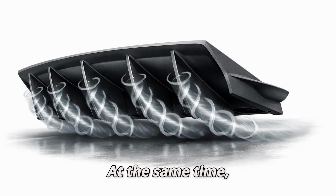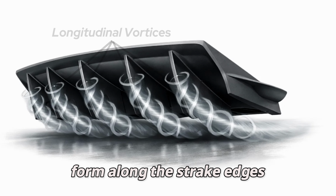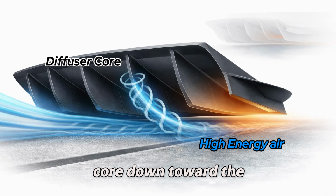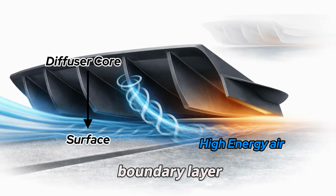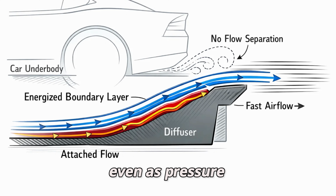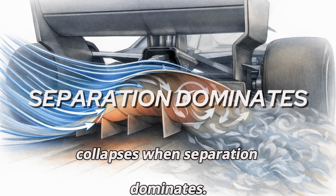At the same time, strong longitudinal vortices form along the strake edges, pulling higher energy air from the diffuser core down toward the surface and feeding momentum back into the boundary layer. This continuous re-energization helps the flow remain attached even as pressure rises aggressively through the diffuser. But even with those three-dimensional effects, diffuser performance still collapses when separation dominates.